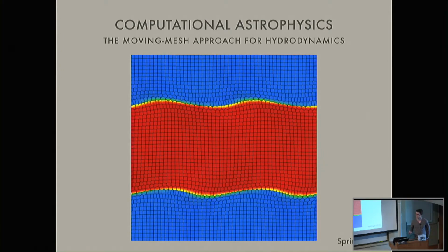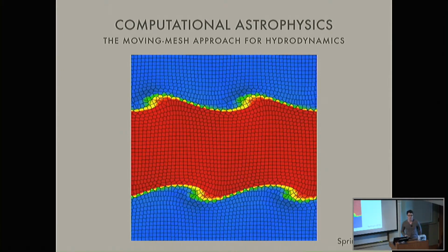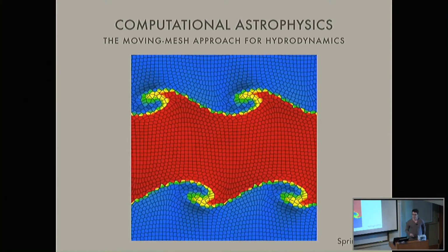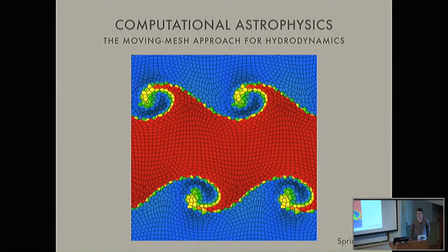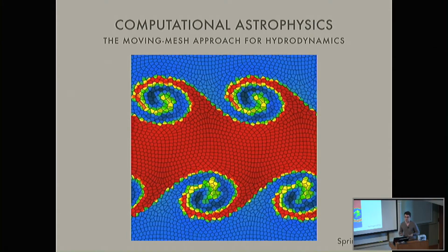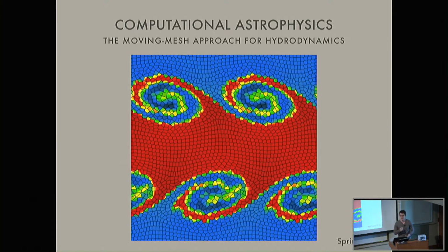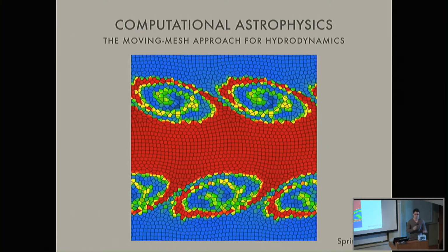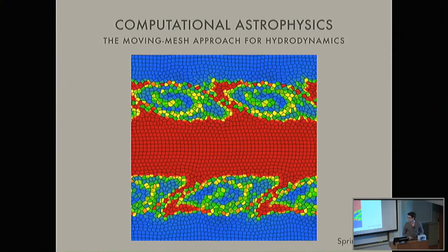In practice, the velocity is given by the fluid flow, which gives you a Galilean invariance in your code. You would now say, okay, the Euler equations are obviously Galilean invariant. However, this is not the case for the discrete version on a fixed Cartesian grid.